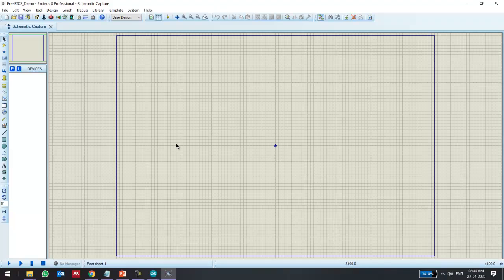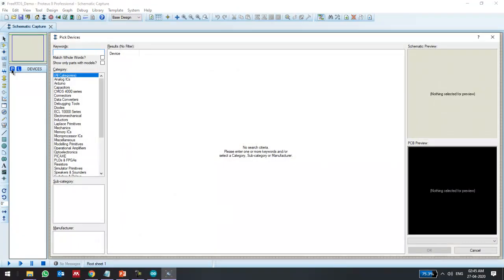And for the analog read operation, we are going to need a potentiometer. One end is connected to the supply, and the other end is connected to the ground. The middle pin will be taken as an input to the analog channel A0. Let's do those operations. First we need to access various parts that are required to implement this example. So get into the parts, type Arduino.